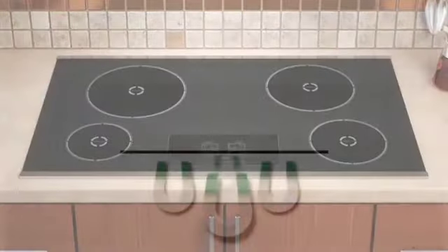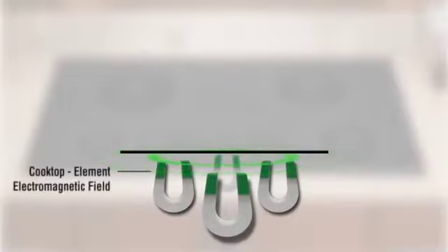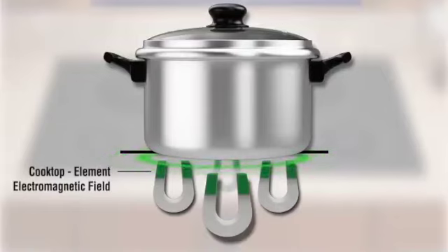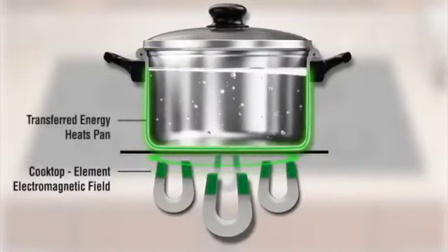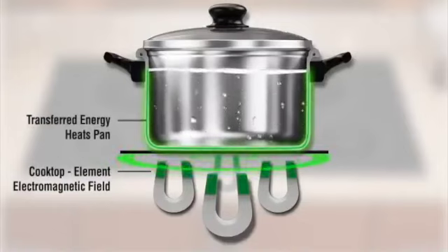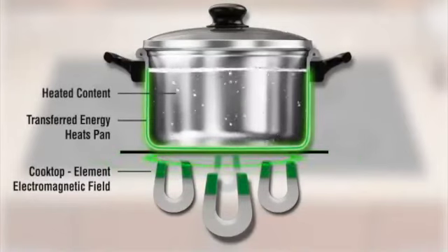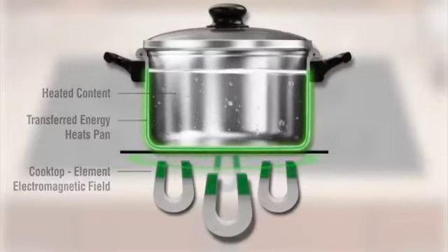Induction cooking relies on the principles of magnetic induction. Induction takes place when eddy currents are created from the presence of an oscillating magnetic field, as denoted by Faraday's law of induction. These induced currents dissipate heat by the Joule effect. Current flows in the cooking vessel due to the low resistance of the metal, with power dissipation given by power is equal to current squared times resistance. This process allows energy to go directly from the coil to the cookware without dissipating through the surface.